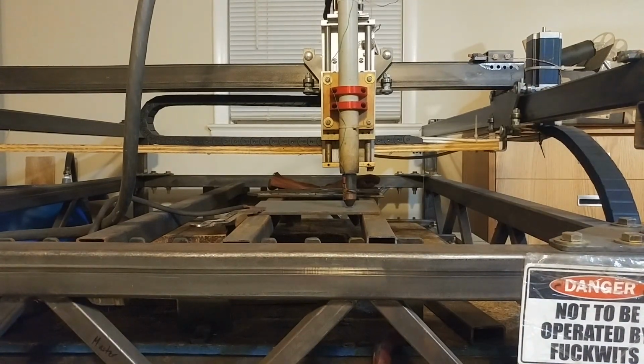So the idea is, with a few more additions to our HAL files, we can give ourselves 2 buttons on the controller that will let us bump the torch up and down even while we're in the middle of running a G-code program. And that'll let us keep the torch in the correct zone for cutting, even if the plate is kind of warped or sloped or just not completely parallel to the gantry. And we want to do that because plasma cutters are pretty picky about their Z height, and they want to skate just barely above the plate while they cut.